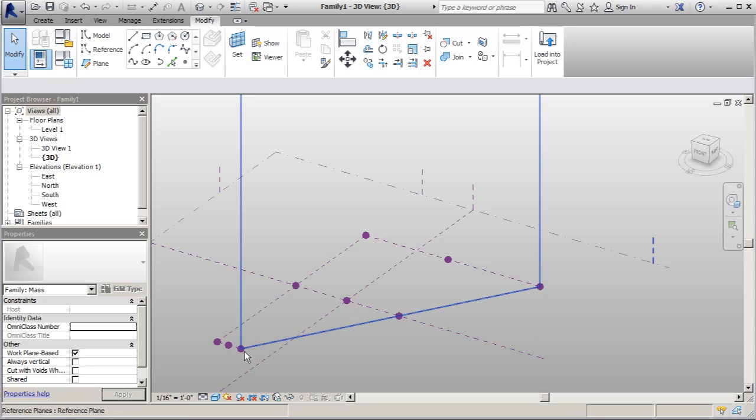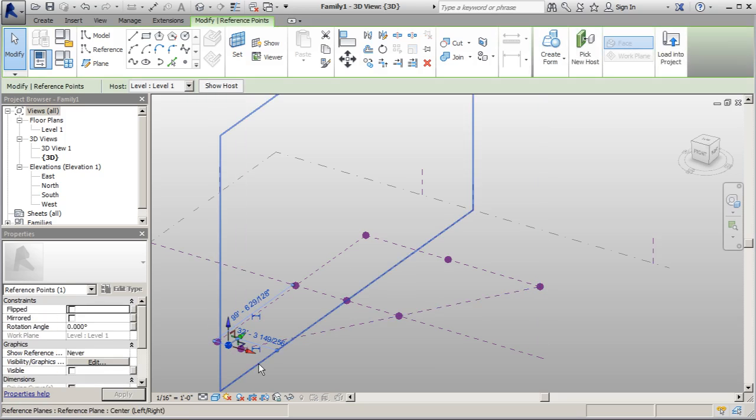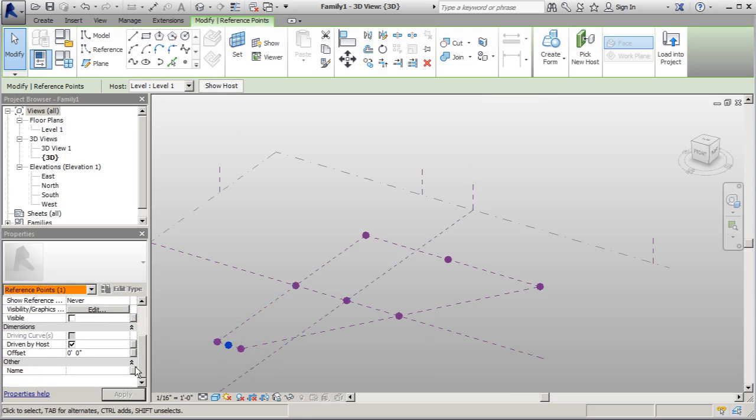But before I'm able to do that, I'm going to go ahead and offset this middle so that when we're creating our spline, we actually have the very peak of our curve there set. So I'm going to set that to an offset here. We'll say maybe we want that curve. We don't want it to curve too much, but we definitely want it to be noticeable. So we could say maybe 3 feet. And I'll type that in as my offset, and you can see that that offset automatically occurs there.